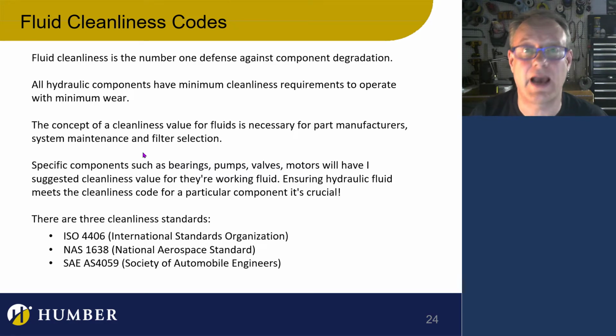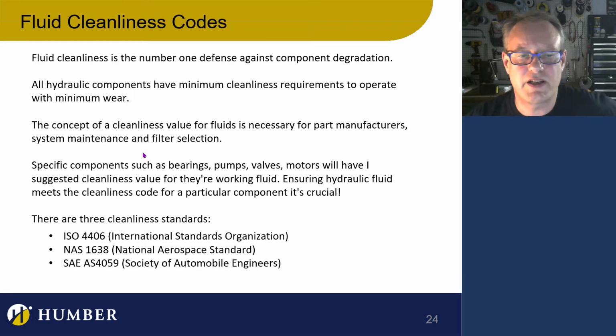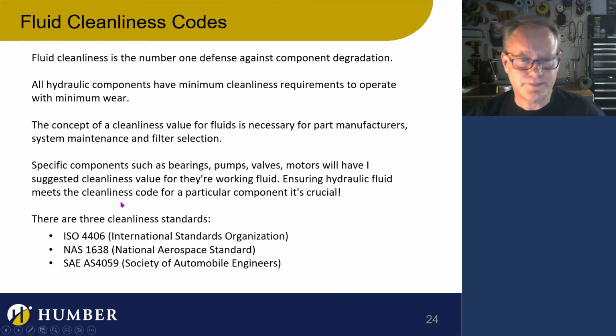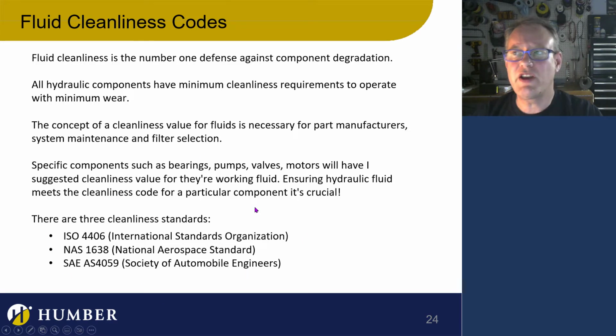cleanliness codes. Yeah, there's a huge industry about cleanliness codes for fluids. It's huge, not just for hydraulic fluids. All these cleanliness codes are for all fluids, all oils, gear oil, or whatever else you're going to have. Cleanliness is a huge thing. There are actually 3 different codes, or standards, pardon me: the ISO, the NAS, and the SAE. I need to go through these with you so that you're familiar with the terminology, and also familiar with the fact that it's so crucially important.